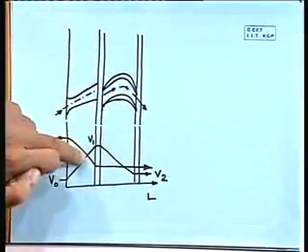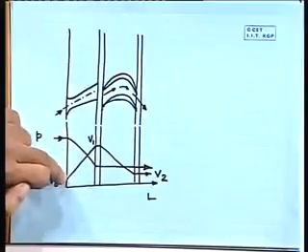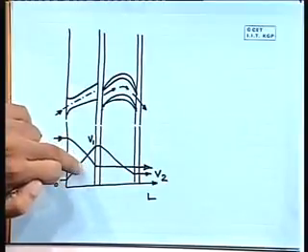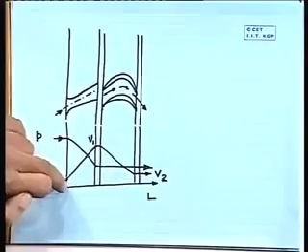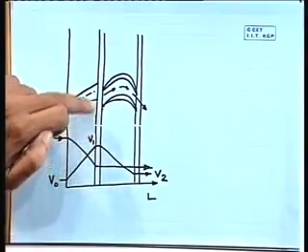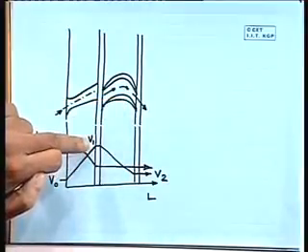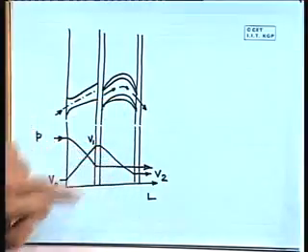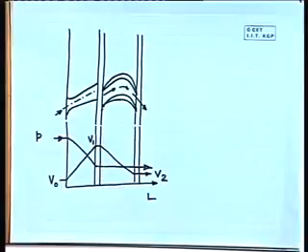In the nozzle there is a drop in pressure and velocity is increasing. Then when the steam is passing through the blade passage, there is a drop in velocity. So, basically there are a number of conversions, and how much will be the inlet velocity and outlet velocity depends on nozzle design and blade design.